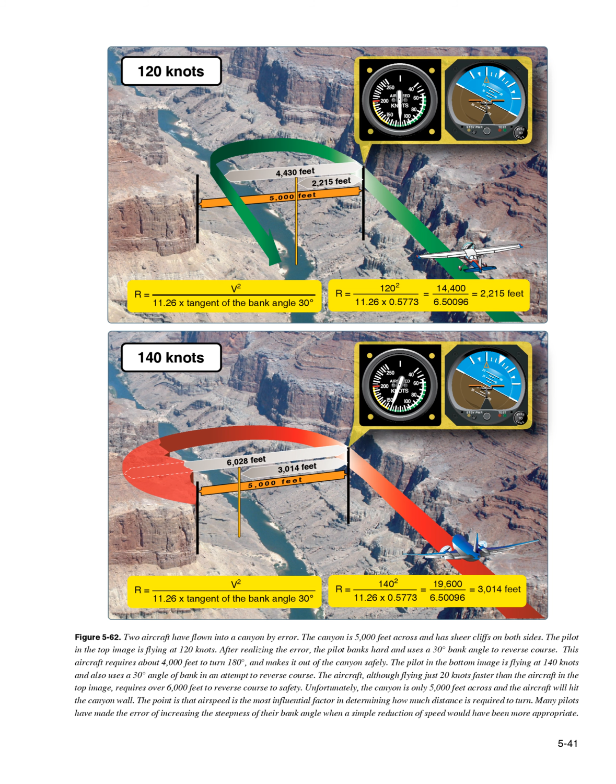The point is that airspeed is the most influential factor in determining how much distance is required to turn. Many pilots have made the error of increasing the steepness of their bank angle when a simple reduction of speed would have been more appropriate.